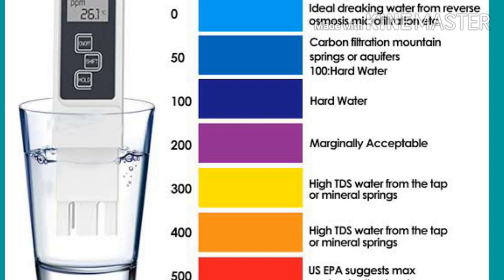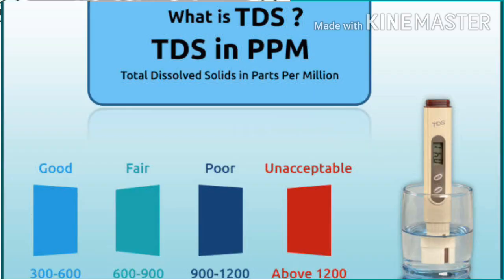However, a very low concentration of TDS has been found to give water a flat taste, which is undesirable to many people. Increased concentration of dissolved solids can also have technical effects. Dissolved solids can produce hard water, which leaves deposits and films on fixtures and on the insides of hot water pipes and boilers.